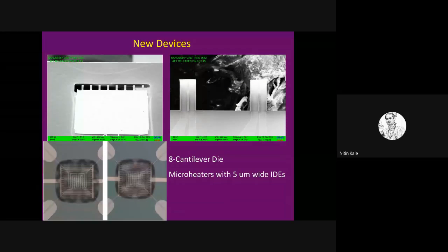They wanted to make an ammonia gas sensor. The overall idea is something like this: metal oxide films are highly sensitive to certain gases, and in fact, I would say many of the gases. However, they respond nicely at elevated temperatures. It's different for different gases and different coatings as well. So the idea was that this micro heater's job will be to elevate the temperature, and the job of the IDs will be to monitor the conductivity of the metal oxide film.